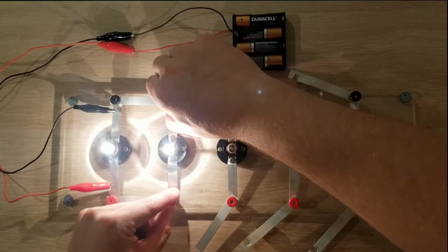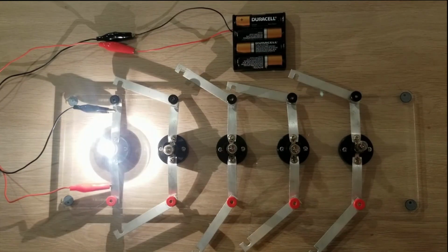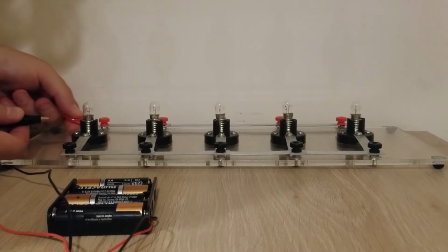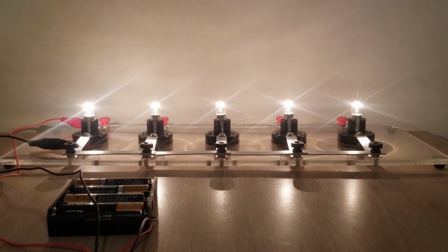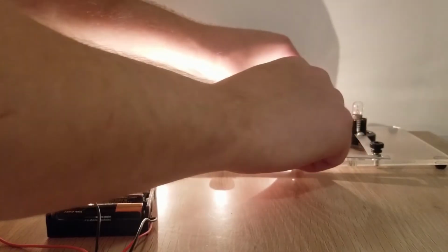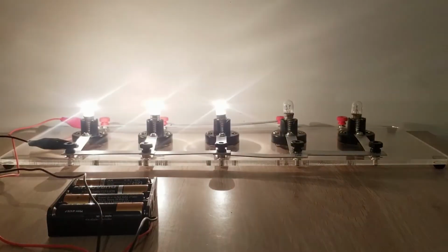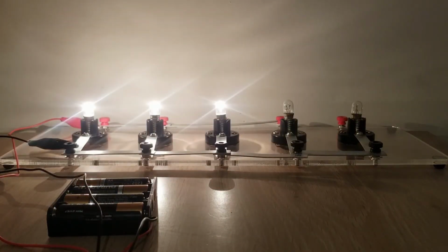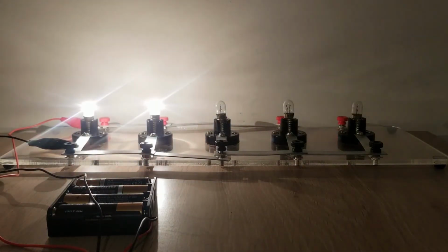As opposed to the series circuit in which every element shares a common current and the voltage is divided across each resistor, parallel circuits work almost the opposite. The current is divided across each branching path on the circuit, but the voltage remains the same throughout every element connected in parallel. Think back to our circuits with the broken bulbs in them. This branching current in the parallel circuit is the reason that the working bulbs in the circuit continued to shine even with the broken bulb in place.